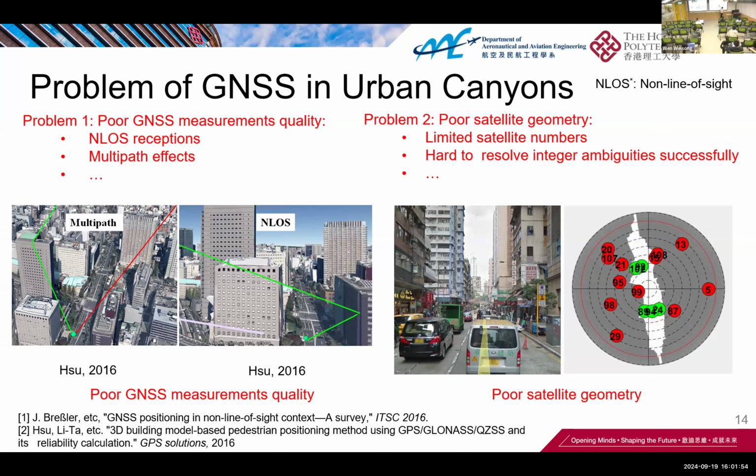So for example, if one satellite is in this direction, but it can still be received here because the signal can be reflected by something like this. So finally you can receive it, but this is going to be crazy. If the signal is reflected several times, the error will accumulate several times, like 1 to 200 meters maybe. Those are called the signal multipath effects.